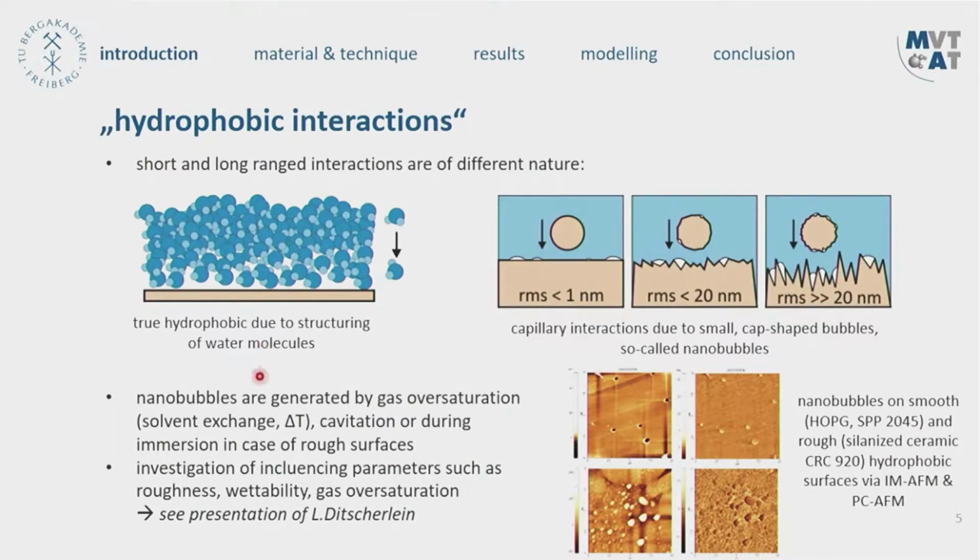We see here the surface of solids, which have a very low surface energy, and the liquid has a higher surface energy. That's why the wetting is poor. The liquid likes to stick to itself, but nevertheless there is nothing in between, so they have to arrange to each other, and this arrangement leads to a special structuring.